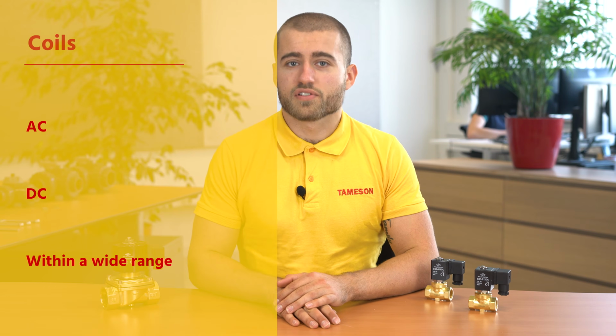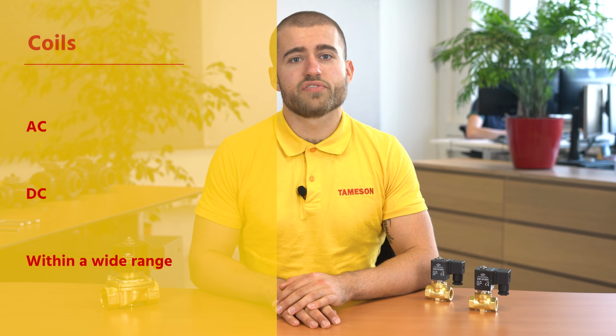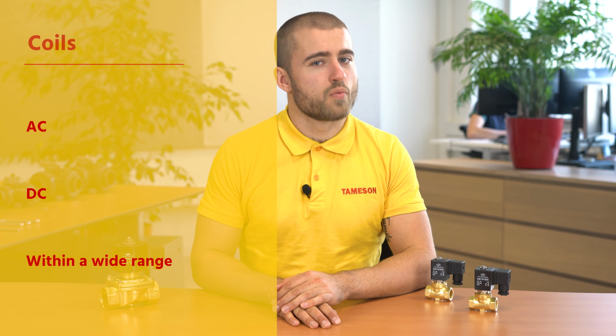And lastly, we will discuss the coils. Coils can be specified for AC or DC voltage within a wide range. Typically, it is decided by what is available at the point of installation. A frequently asked question we get is whether the direction of the flow through a DC coil is important, because most coils have no indication of polarity. And the answer is that polarity doesn't matter. The power supply can therefore be connected in both directions.